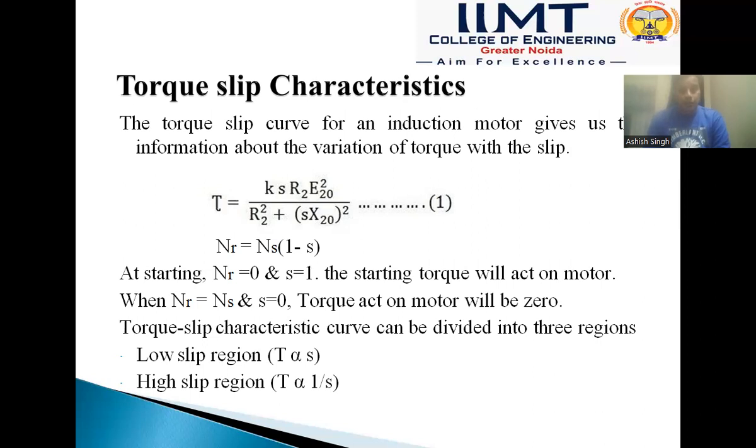And when the rotor speed of the induction motor equals the synchronous speed, at that condition the slip of the motor will become 0 and the torque acting on the motor will become 0, because when we put S equals 0 in equation one, we get torque equals 0. So when we are discussing the torque slip characteristics curve of a three-phase induction motor, it is broadly divided